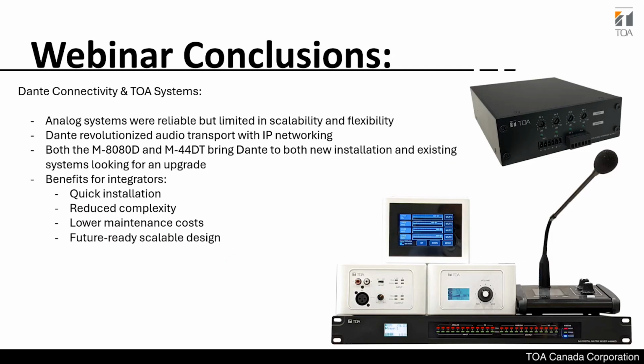So, Dante connectivity with the TOA system: analog systems are reliable but limited in scaling and flexibility. Dante transports the audio through the network using the existing switch, and both the M88DT and M44DT bring Dante to both new installations and existing systems looking for an upgrade.